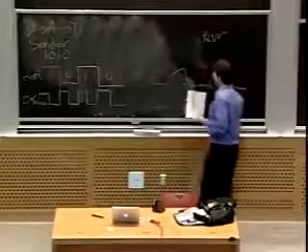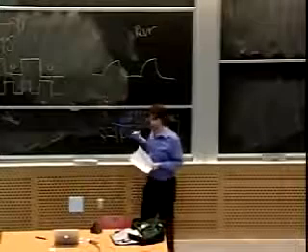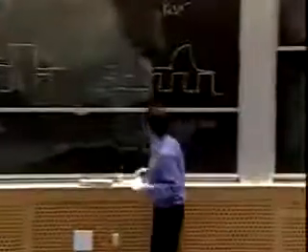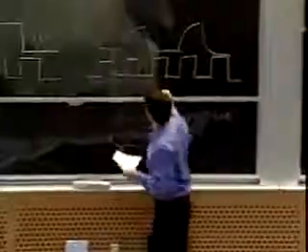each of these nice square waves might have become a somewhat decayed version of its former self. Okay? And now the question is, how are we going to decode this? We don't have access to the original clock signal that was used, but we may know what rate this data was encoded at, so we may be able to generate a comparable clock signal. So suppose we generate a clock signal at about the same frequency, and then try to use that to decode the message, say by looking again at the rising edges.